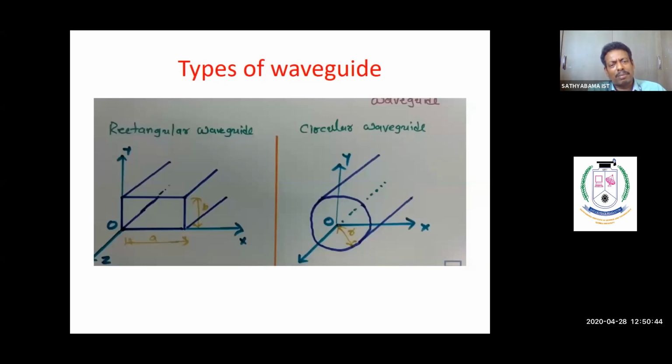But commonly in practical applications, when you take radar or satellite applications, people use TE mode only. In a rectangular waveguide, they always launch signals in the TE mode configuration. The reason is that TE mode has the lowest cutoff frequency. That is, for the same given dimension, you will be able to send lower frequency signals through it.